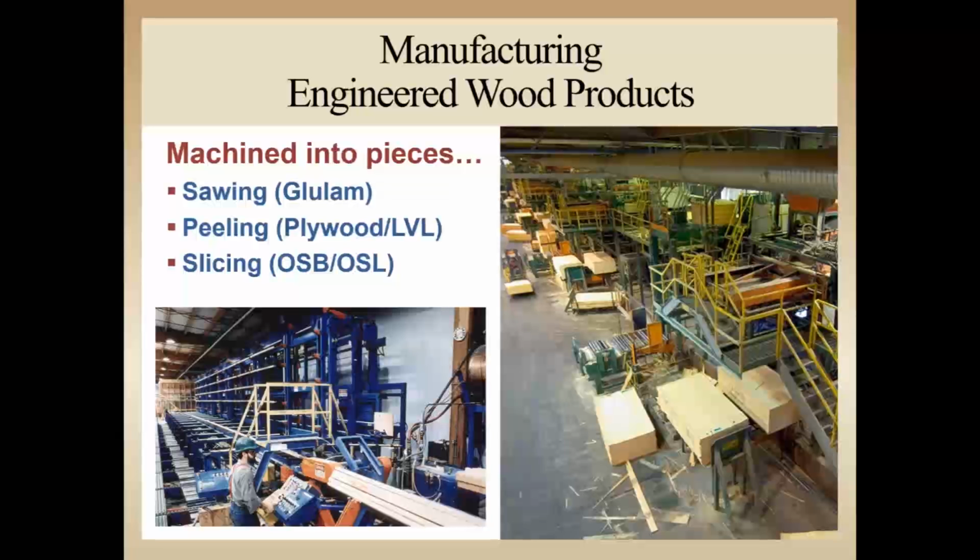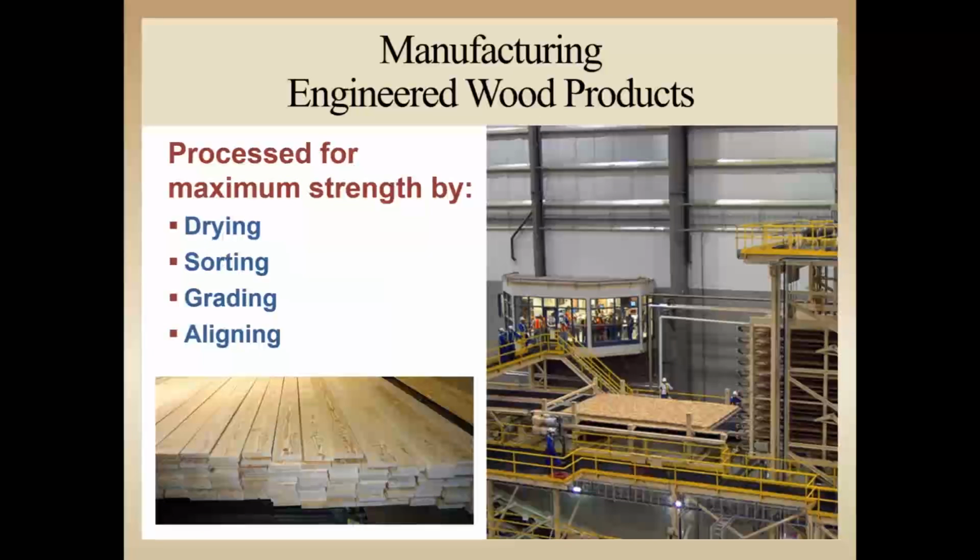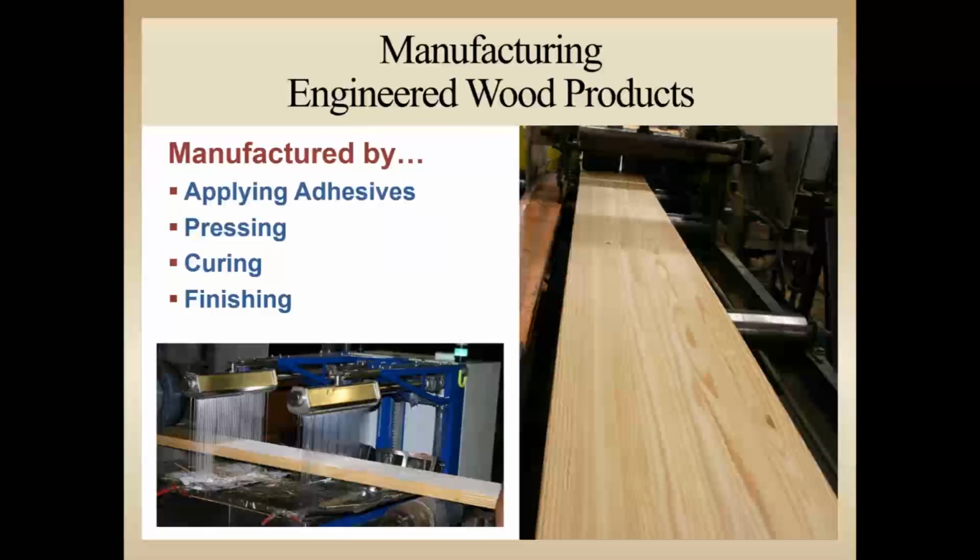The raw wood laminations and strands are sorted by grade and dried so that the resins can effectively bond the laminations or strands together into structural members. The resins are applied to the laminations and strands in a controlled manner to assure a permanent bond. Strong wood fiber plus durable moisture-resistant resins equals high-quality engineered wood products.